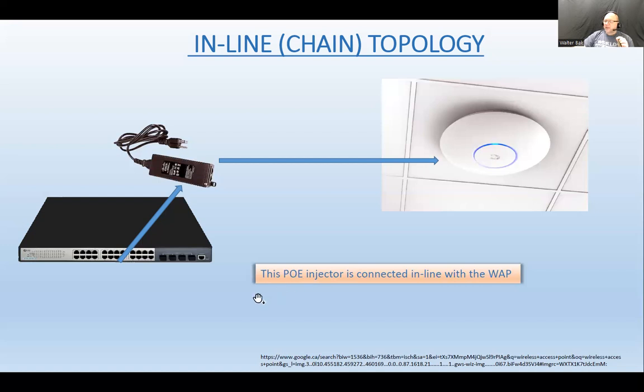So if you have a huge project where you're going to get a whole bunch of VoIP telephones that need power from that or whatnot, then the client might decide to replace the switch with one that is capable of jacks with the PoE in them, power over Ethernet. But sometimes the whole system works and it would be too big of an operation to replace it just to add one device that needs PoE. You can use a device that's called a PoE injector.